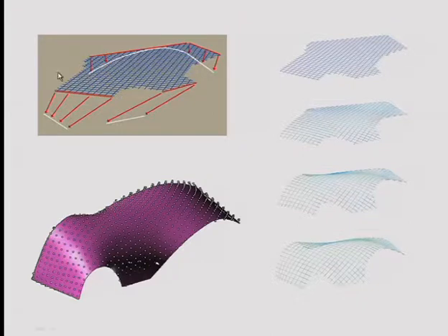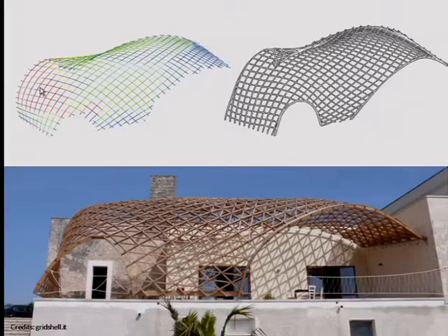There are tools now with Grasshopper and Kangaroo. There is a tool, and there are also other external tools that allow you to simulate physical phenomena. So you have some prescribed displacements, and you know what the shape of your flat grid is. Out of that, you get this Rhino geometry. All right? And the computer simulates the steps for you. You can also calculate exactly where the structure is most stressed and when it's going to break. So the red is generally bad, and blue means generally good.